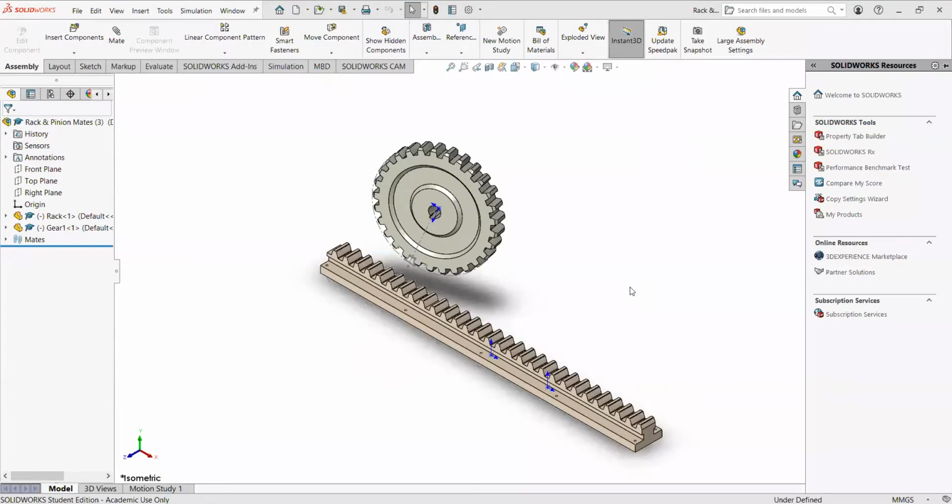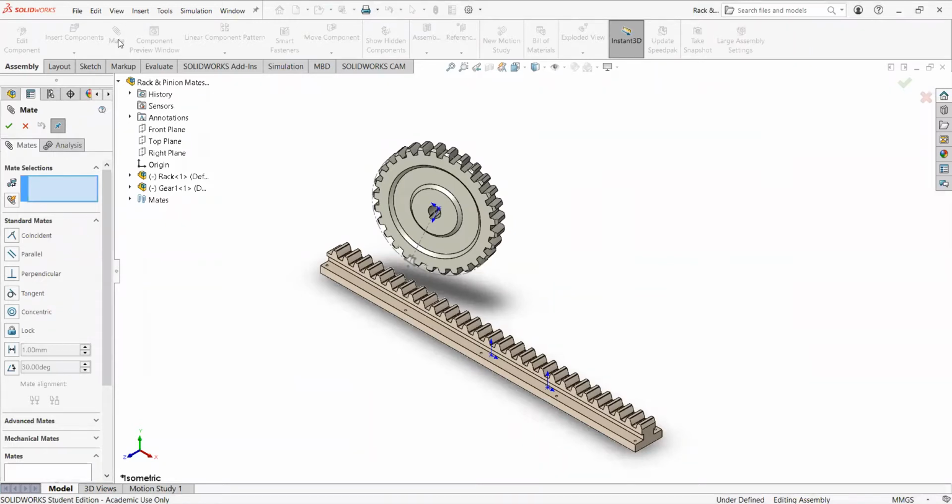When you open the Solidworks rack and pinion mate file, you will see they are not attached to each other to create a mechanism. So we will create this mechanism, and we will create the visualization, which is very important, so we can analyze and see how these products will be assembled to each other. So we're gonna add multiple mates. Start with the first mate, go to the Feature Manager and select the mate. Now expand both the rack tree and the gear tree.